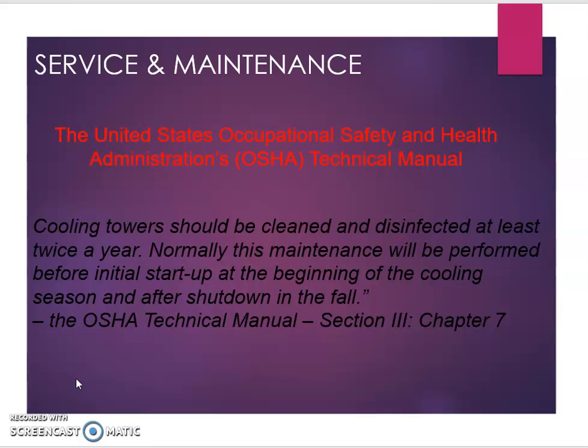So like I said previously, we have to perform the maintenance and servicing for the cooling tower at least one time every 6 months, which is 2 times a year. Normally this maintenance will be performed before initial startup at the beginning of the cooling season. This is the case for a 4 season country, and also after shutdown in the fall season.